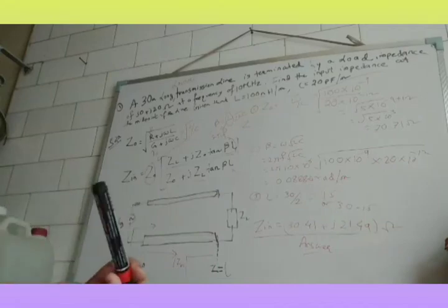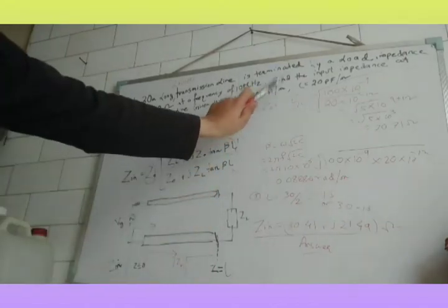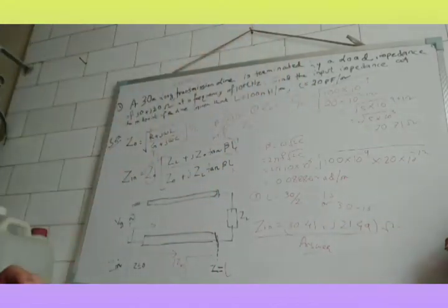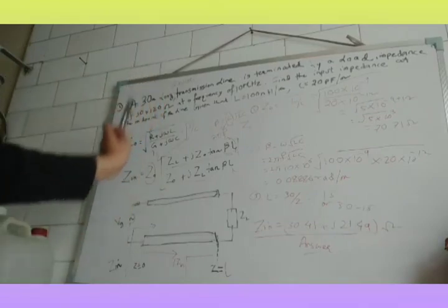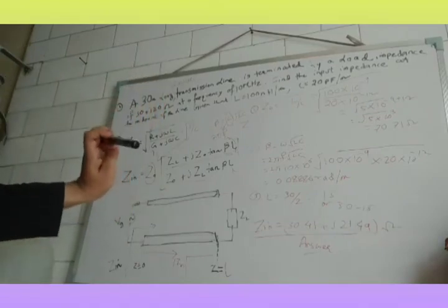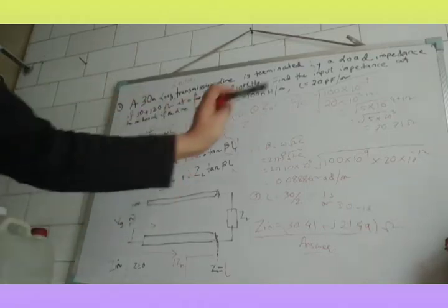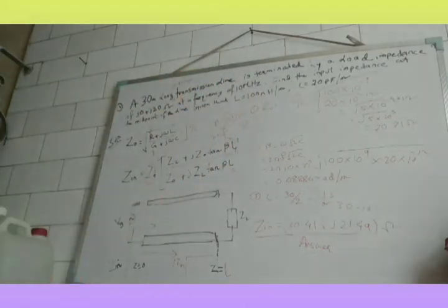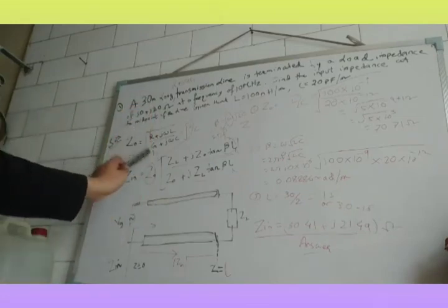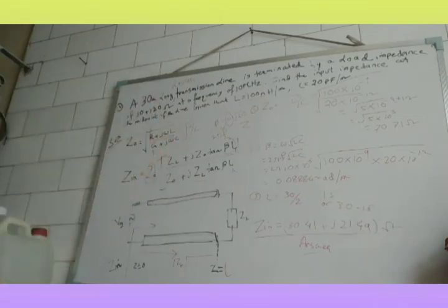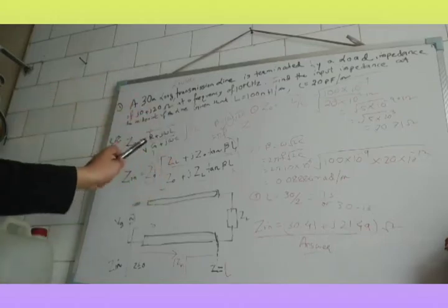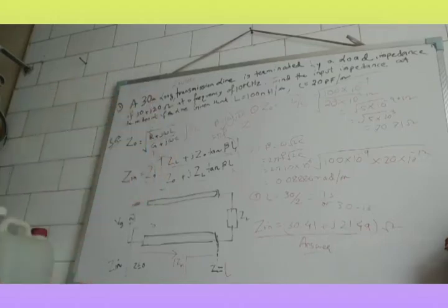One thing I need to mention here, one is this unit per meter. Another thing is for a lossless transmission line, R equal to 0, G equal to 0, because G captures the leakage current and this gives a drop across the line. So for lossless, these two parameters will be 0, because for lossy, this will have some finite value.